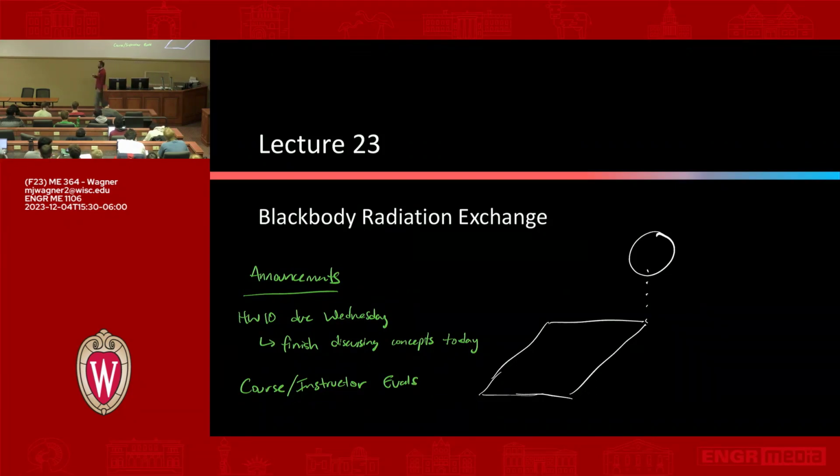So remember that we're trying to get the pieces to all add up. So in this case, what you could do is take advantage of symmetry. All right, so this is a big hint for this homework. I could compute the view factor for the quadrant here of a rectangle. I could also do view factors for similar quadrants like this. And together, all four of those quadrants, you add them all up, that's the total view factor from the sphere to this surface. So that can be one way that you piece things together. So maybe that's the view factor from the sphere to the tube.